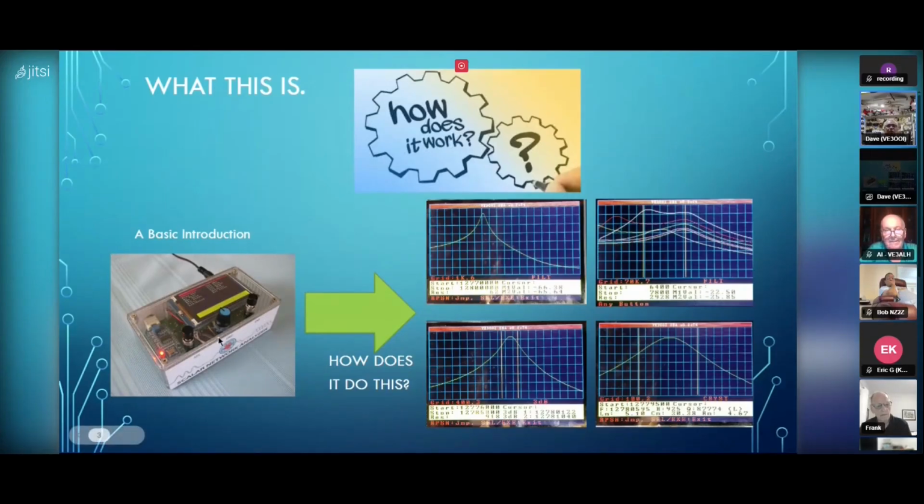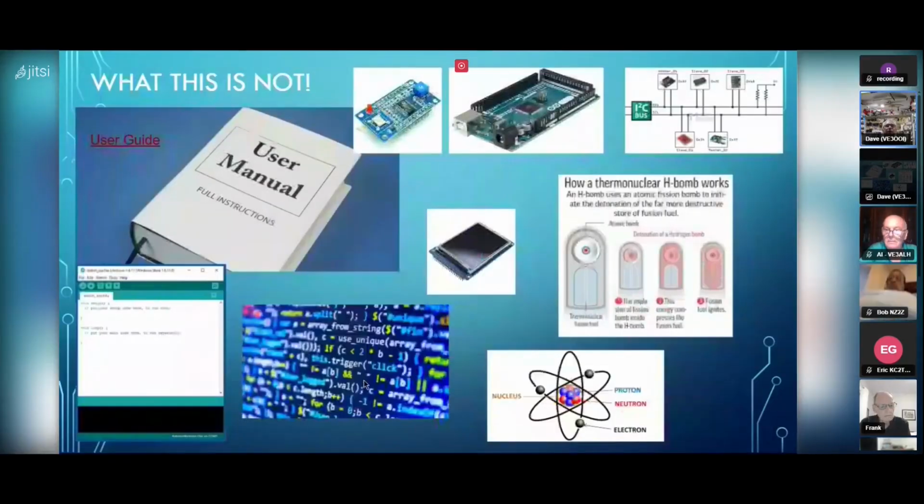And so the PARC SNA, for those who don't have it or haven't used it, generates a bunch of charts, and I'll go through what some of the charts are. The nice feature is that it can do overlays, where we can put multiple charts on one screen. It'll actually give you the 3 dB points of a filter, and you can see it here: start, stop, 3 dB 1, 3 dB 2. And here it's giving you the crystal motional parameters of a crystal. So it's pretty useful, I think.